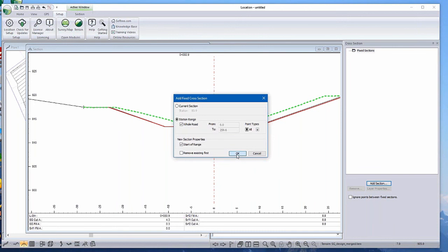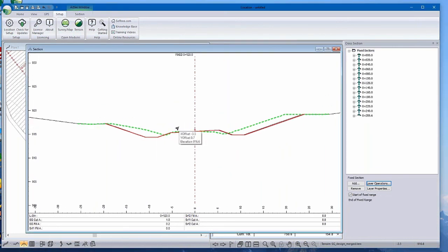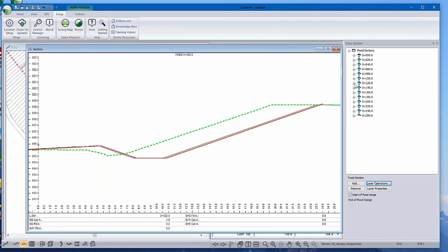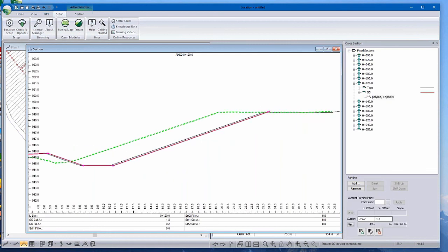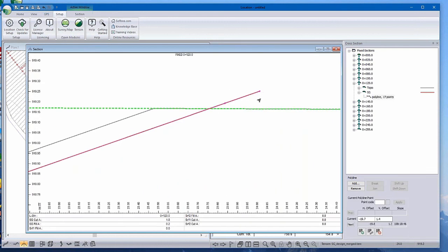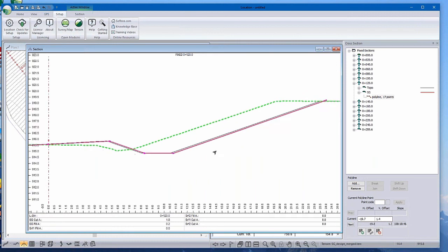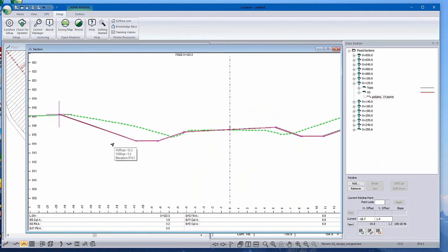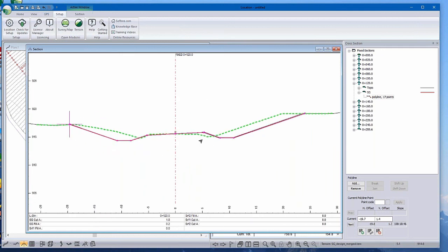And yeah, so now you can go in and if you wanted to tie off the survey, which is in the subgrade, topo is actually the design surface, so you could come in here and fix things like this. And again, you can calculate volumes. And you can switch the surfaces. I could have, instead of design versus built, compared built versus topo, maybe for pay quantities and things like that.